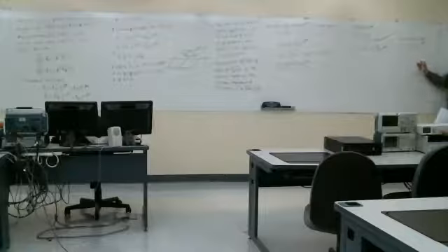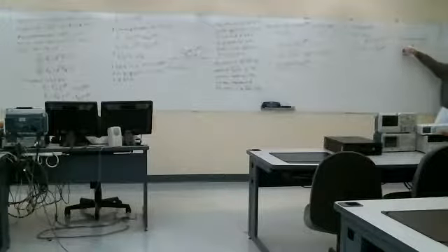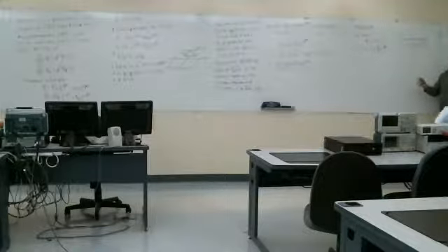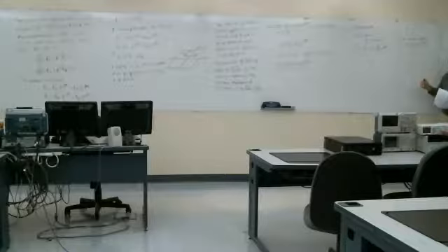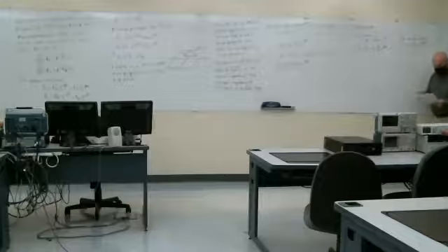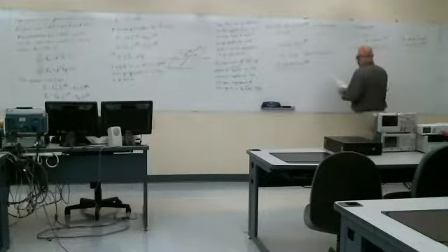Or it might be propagation in an xy direction, and then using these cross product rules, I can figure out the directions of E and H. The other thing here is that with propagation in the z direction, restricting E to be just in the x direction appears to be fairly restrictive. But I can just rotate the xy plane so that my x-axis is aligned with the direction of E. So I'm being fairly general here in terms of my choice of coordinates,